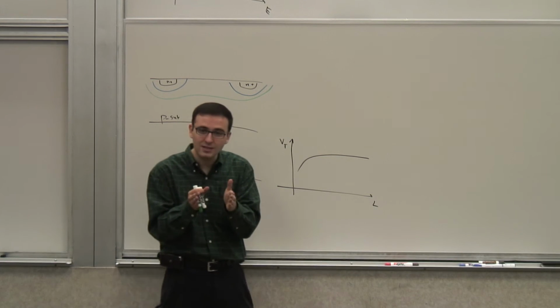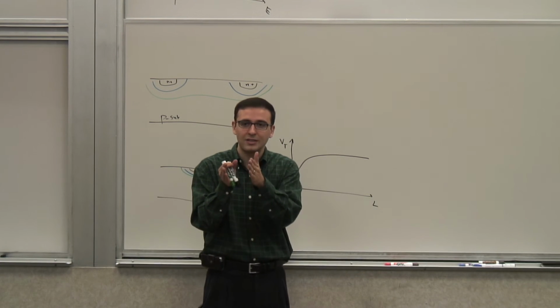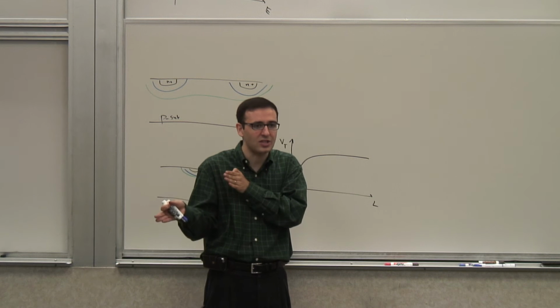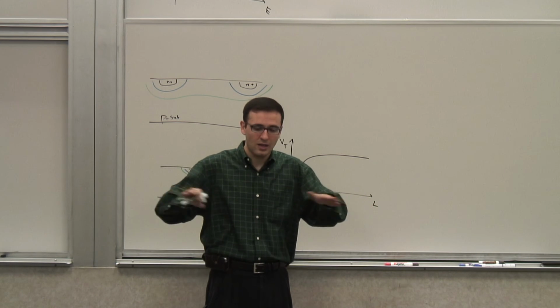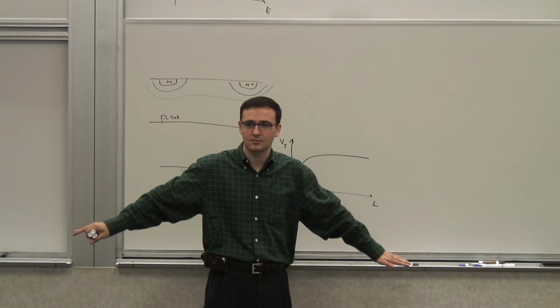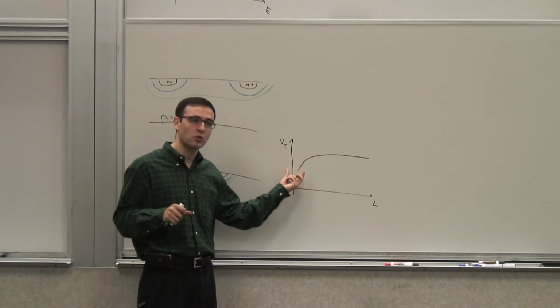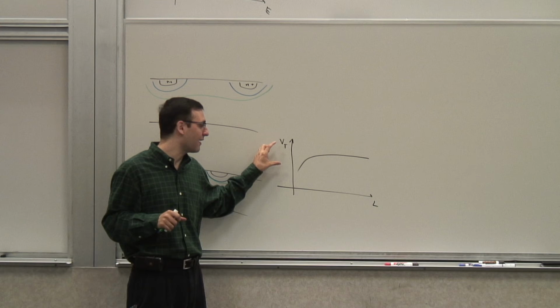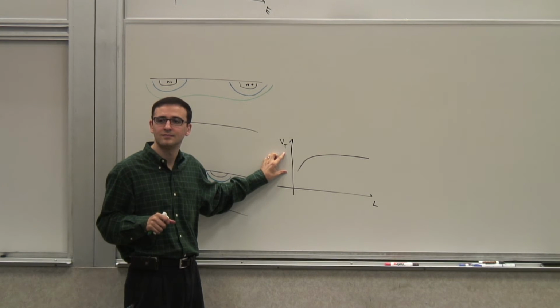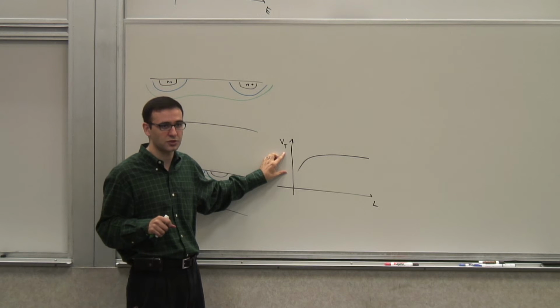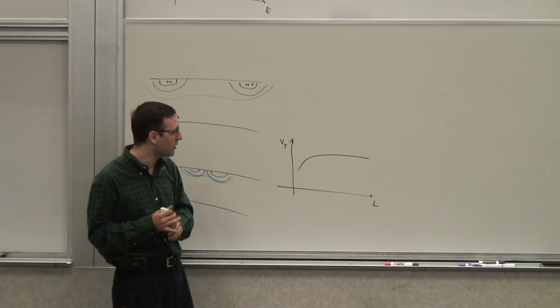But in a given process technology, the implant charge is fixed. You can't change that once the chip is made. It's fixed for all transistors because it's a batch process. So the transistors that have shorter channel length are bound to have smaller VT. The VT is not even constant once you go to short channels. So that's something to keep in mind.